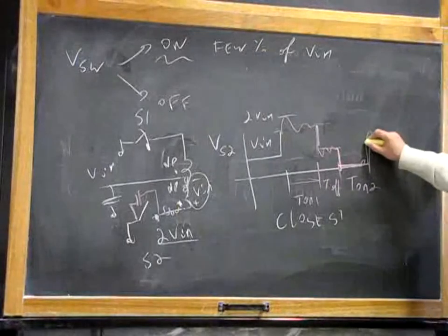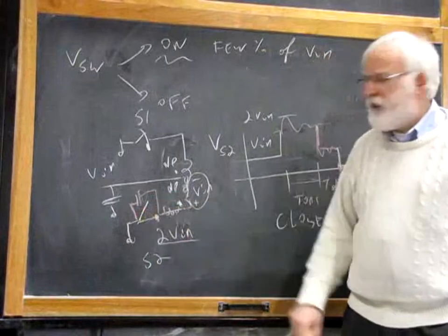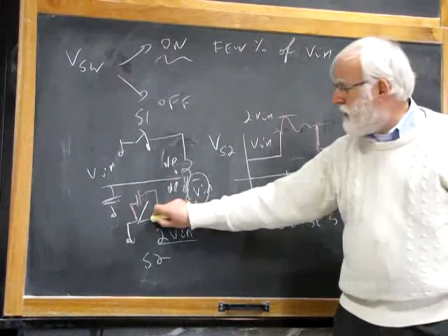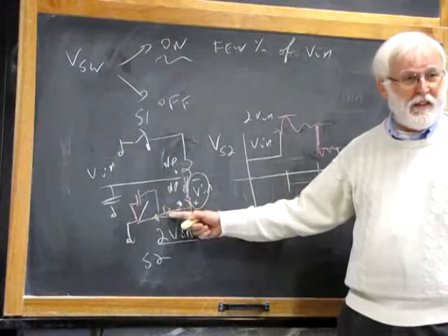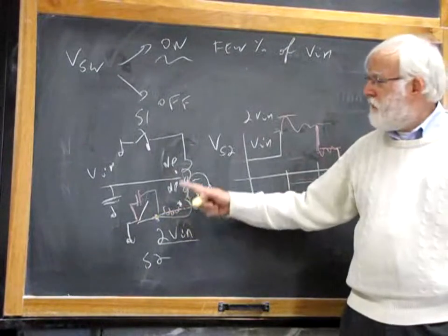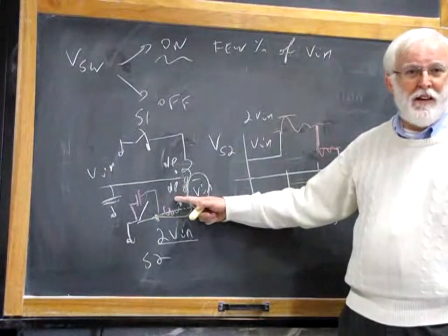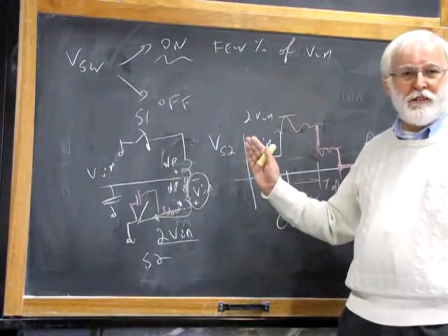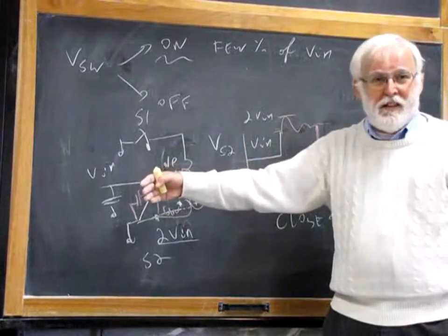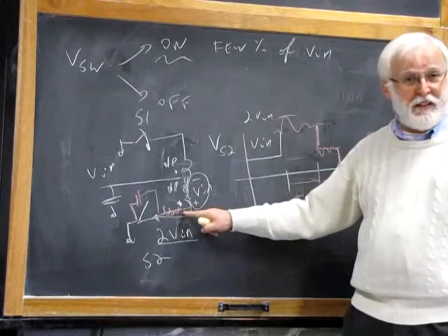Because at this point, look at the circuit how it is. You have this switch closed, you have a lot of current flowing through these parasitic inductance, through these leakage inductance. Why a lot of current? Because this is a medium power, low voltage topology. So you can have a lot of power going to the secondary side with a low input voltage. Low input voltage, a lot of power means large current. And this large current flows to these leakage inductors.